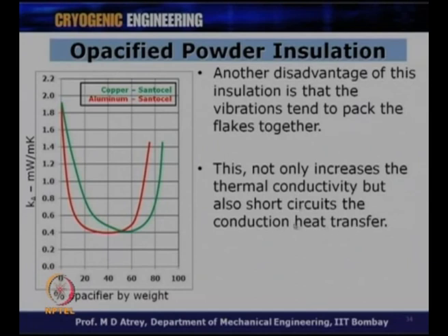All right. So, a lot of flakes together means you have got more conduction happening out there. So, one has to ensure that these flakes are evenly distributed, first thing, and also ensure that no vibrations are given to this particular vessel which has an insulation of opacified powder. But if you get vibrations, then these problems can be faced over a period of time.